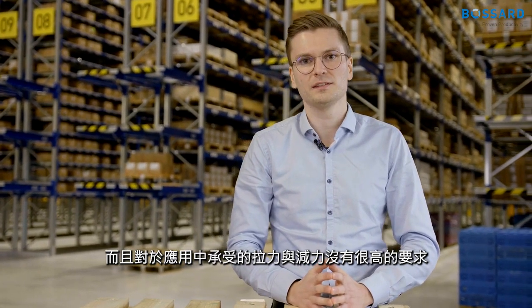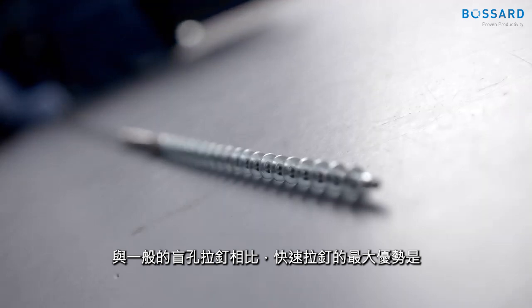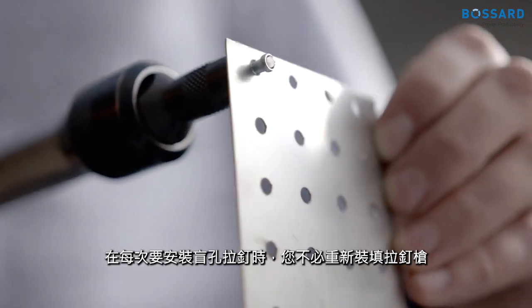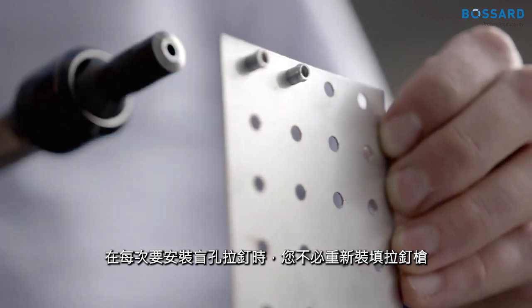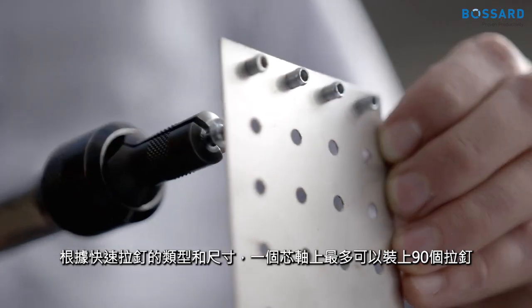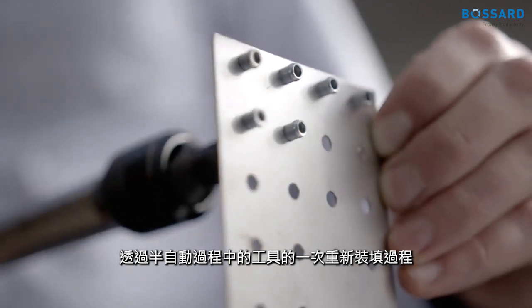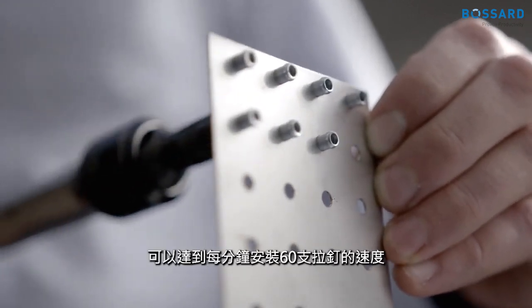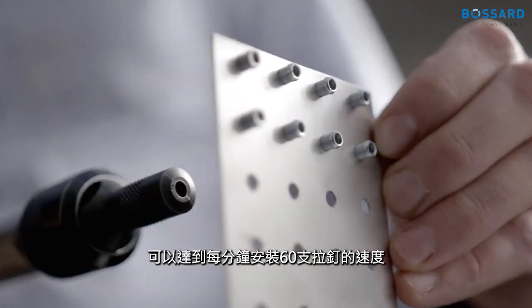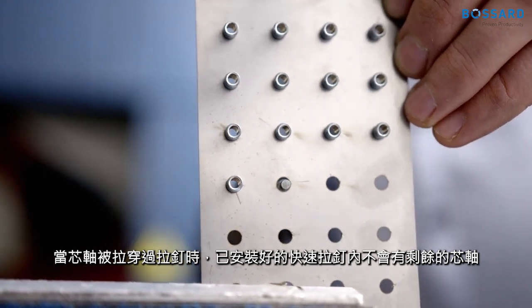Speed rivets are used in applications where manufacturing speed is required and we don't have high requirements in regards to tensile and shear forces within the application. The big advantage of speed rivets against normal blind rivets is that you don't have to reload the installation gun every time you want to install a blind rivet. Depending on the speed rivet type and size, up to 90 rivets can be mounted on one mandrel. That results, with one reload process of the tool, in an installation speed of up to 60 rivets per minute in a semi-automatic process.